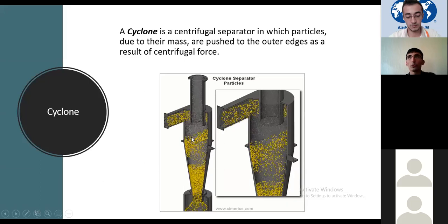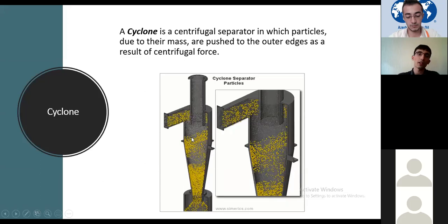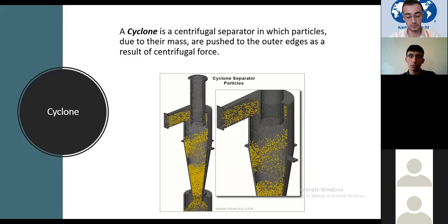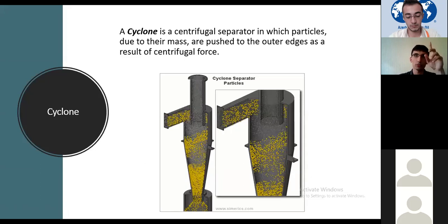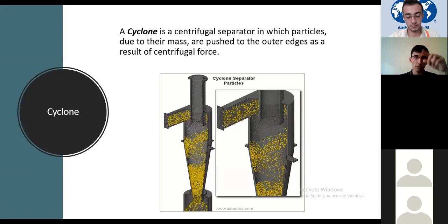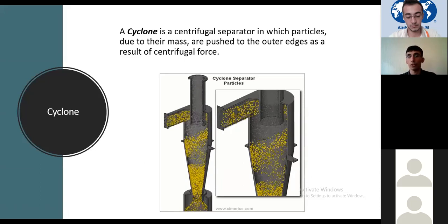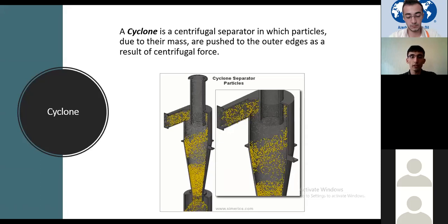We use nitrogen gas in our dryers to dry the polymers, and of course nitrogen flows from the top side of the dryer together with fines, the small polymer particles again, and then we send it directly, before the scrubber, into the cyclone.